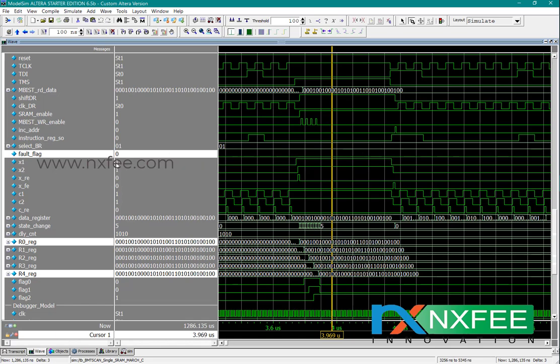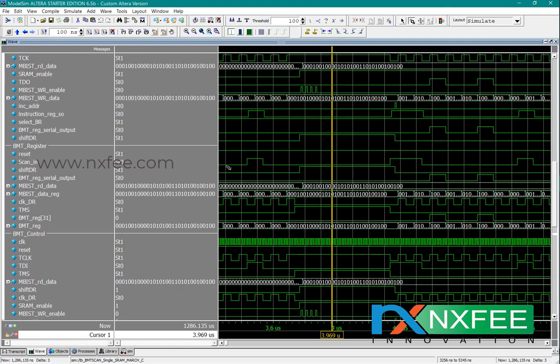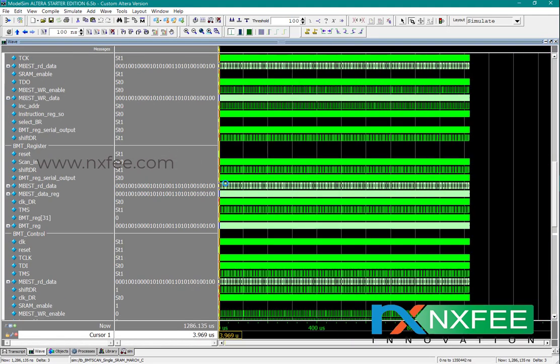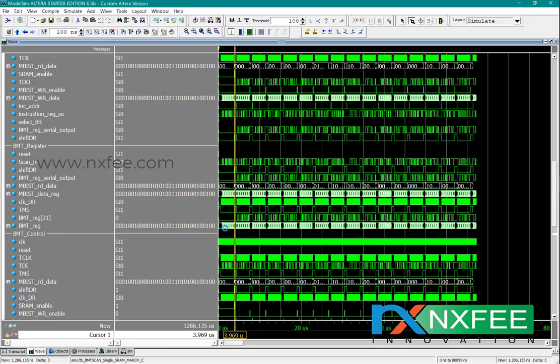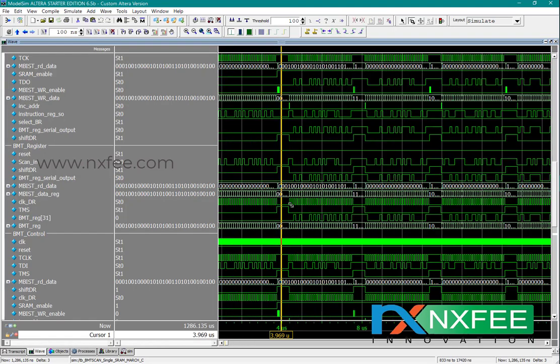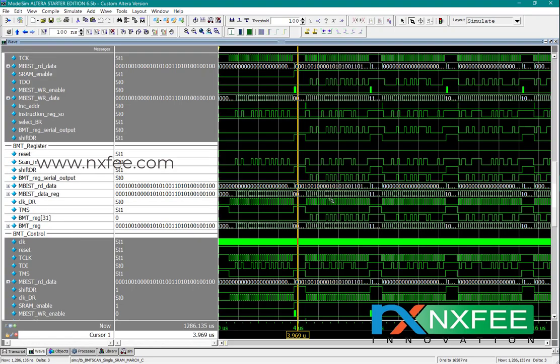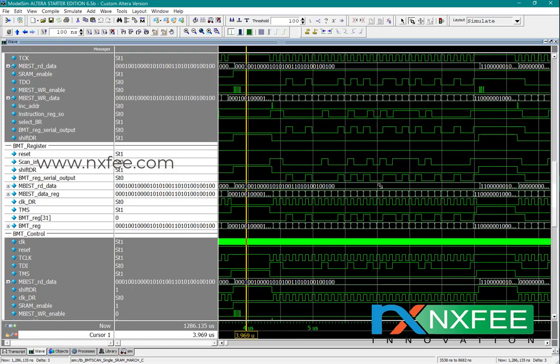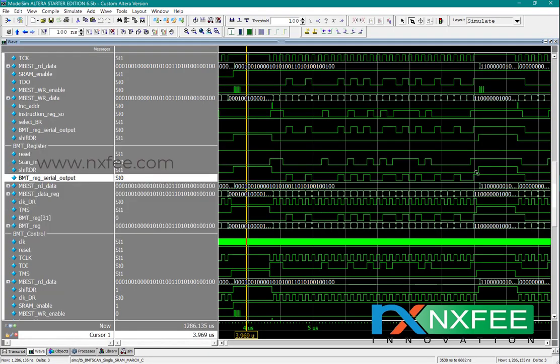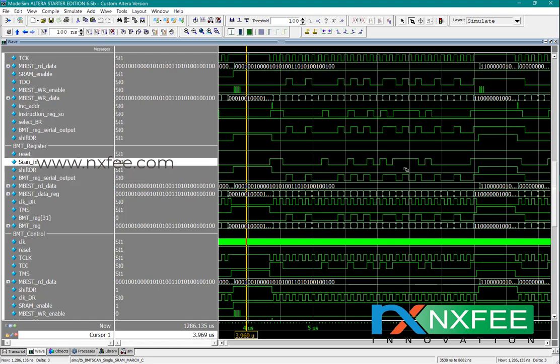With the support of these two signals, the BIST registers will generate output in the second period. Here this one is the second period. The BIST registers work in parallel mode. At the time of data shifting to the output, it is also receiving input from the scan-in. So now it's ready for the second test sequence.